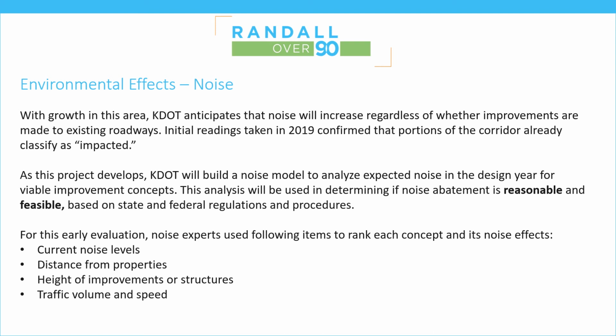For this early evaluation, noise experts used the following items to rank each concept's effect on noise: current noise levels. Improvements in locations which already have higher noise levels will receive a lower score. Distance from properties. The greater the distance, the less likely a property is impacted. Height of improvements or structures. Noise will tend to travel further if improvements are elevated. Traffic volume and speed. The higher traffic volumes and speeds will generally generate higher noise levels.